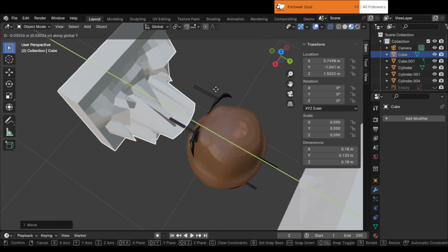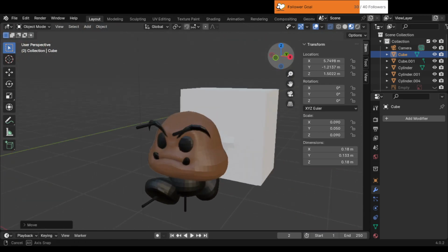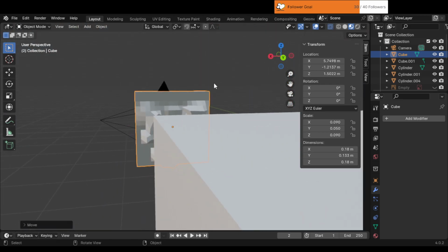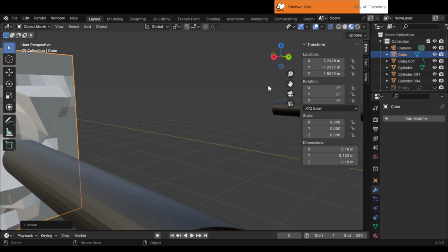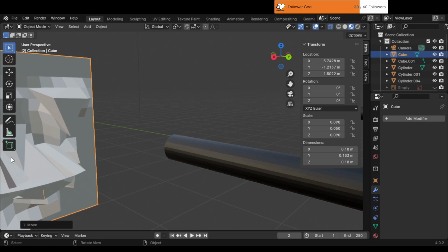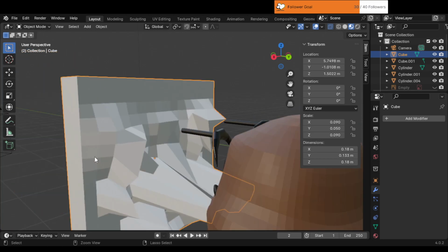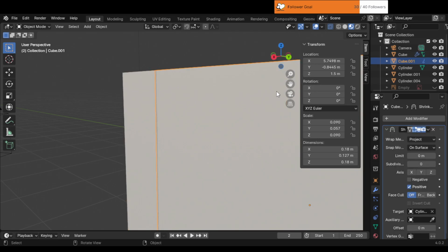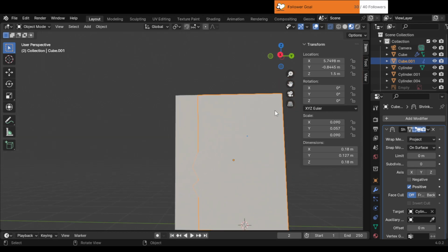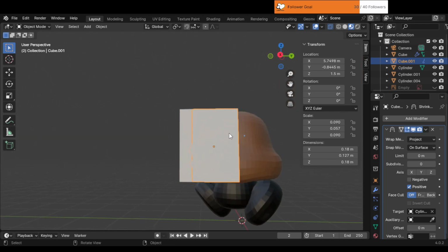Conclusion. The wrap created using the shrink wrap modifier can conform to the shape of your subject and potentially save its shape for later printing. However, the quality and accuracy of the wrap will depend on how well the wrap mesh is set up, as well as the settings and adjustments you make using the shrink wrap modifier. Ensure the wrap is smooth, conforms closely to the subject's shape, and is free of non-manifold geometry for successful 3D printing.